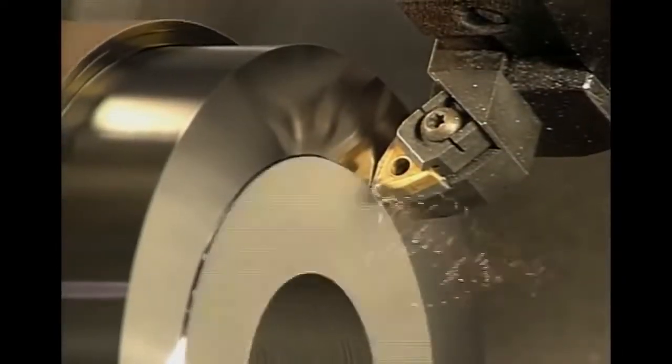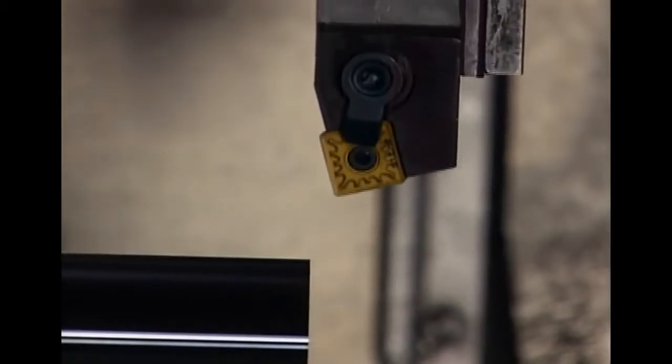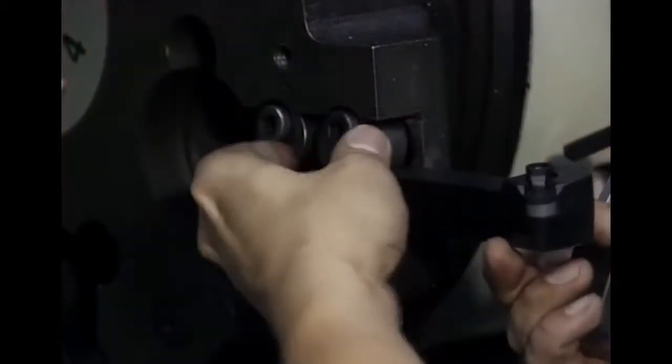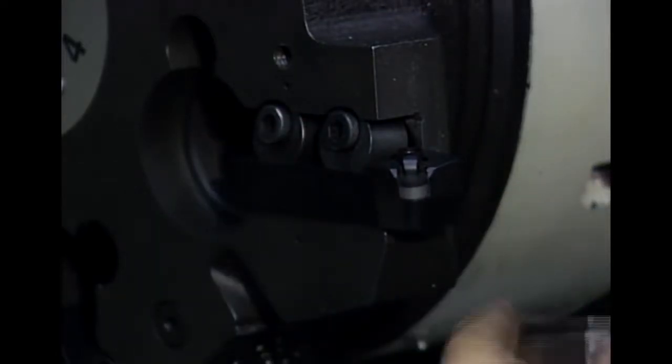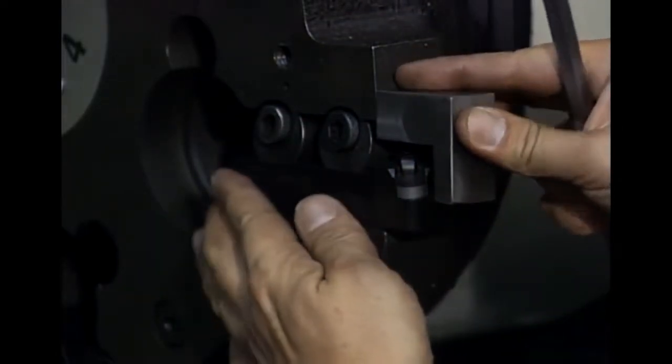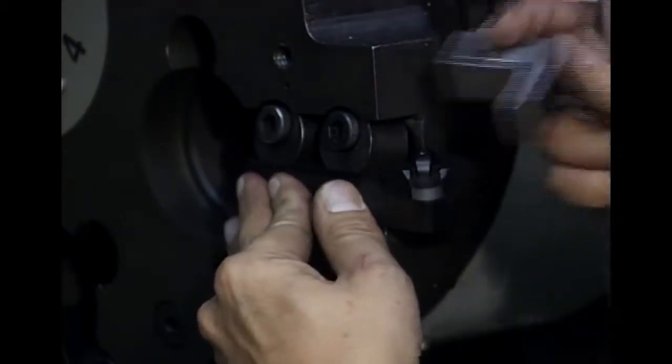Some tool holders are designed for facing. The offset style tool holder lets work be performed closer to the chuck jaws and is generally chosen over the straight shank. Tool holders and boring bars should be positioned as far back in the turret or tool block as possible to maximize support. Overextended tools chatter and cause insert breakage.